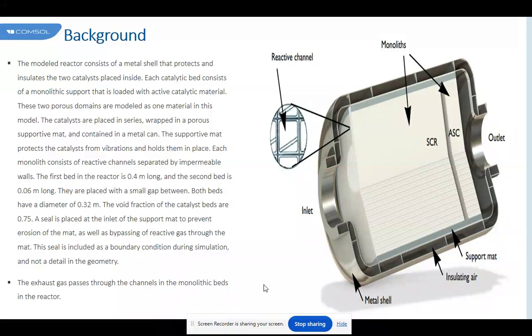This presentation is organized as follows. In the next section, we present a one-dimensional two-phase model of the monolith reactor with position-dependent transfer coefficients. Since metallic monoliths used in applications have sinusoidal channels for which the transfer coefficients are not readily available in the literature, we present some computed new results on the asymptotic Nusselt and Sherwood numbers for sinusoidal channels of various aspect ratios.